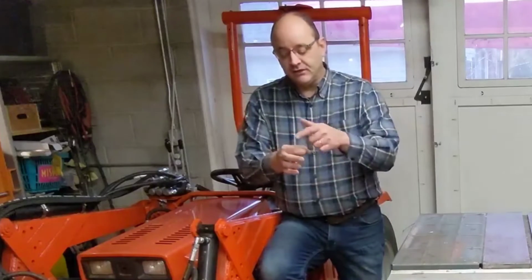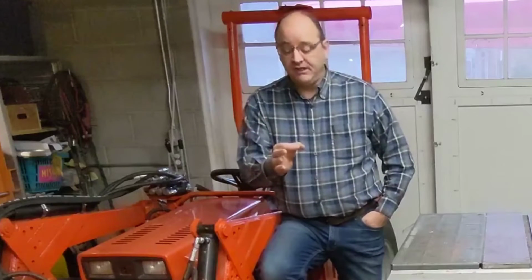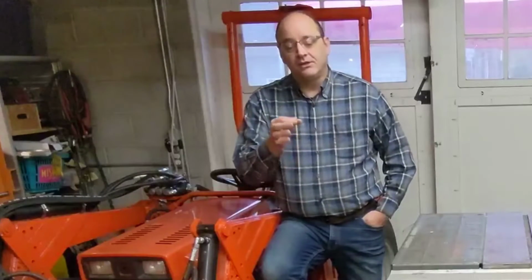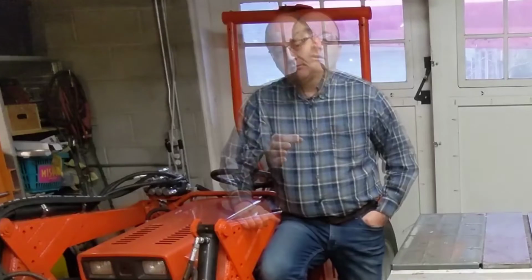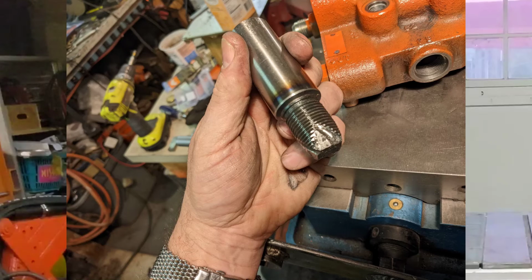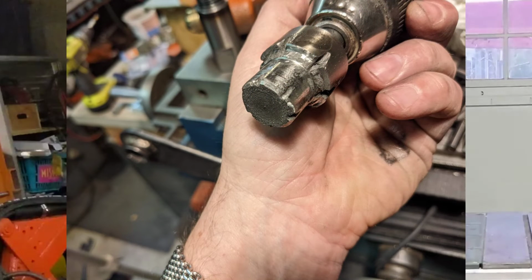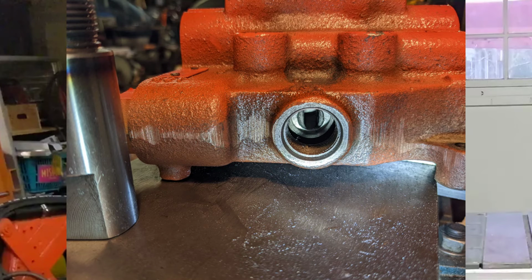Meanwhile, the outer wall of the valve will be threaded and will be chamfered so that a number 10 SAE fitting can screw in there and the O-ring will seal against the bevel. Our threads have to be clean and strong enough to hold that fitting firmly against the 3,000 psi pressure trying to pop it out of there. And our face and chamfer have to be perfectly smooth so that that O-ring can seal against it. So I'm going to need two different specialty tools. I'm going to need a 7/8-14 tap to create those threads, and I'm going to need a reamer to prep the hole for the tap and create that smooth outer face and chamfer.